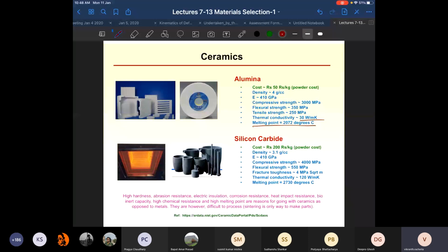Let me check once. So why is this sintering process used? You were talking about the sintering process. See, what can you say about the melting temperature of ceramics in comparison to that for metals or plastics? So it's very high. It is higher than the others. So what does that mean? Like melting a material and casting it into a mold is not really an option for ceramics.